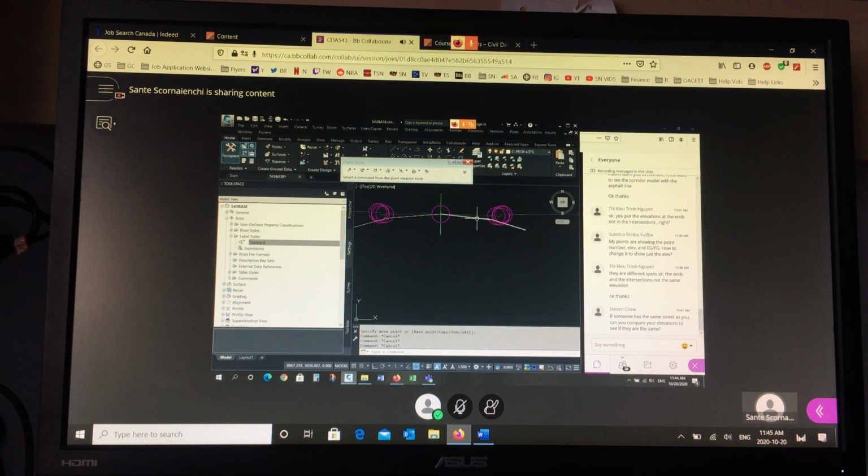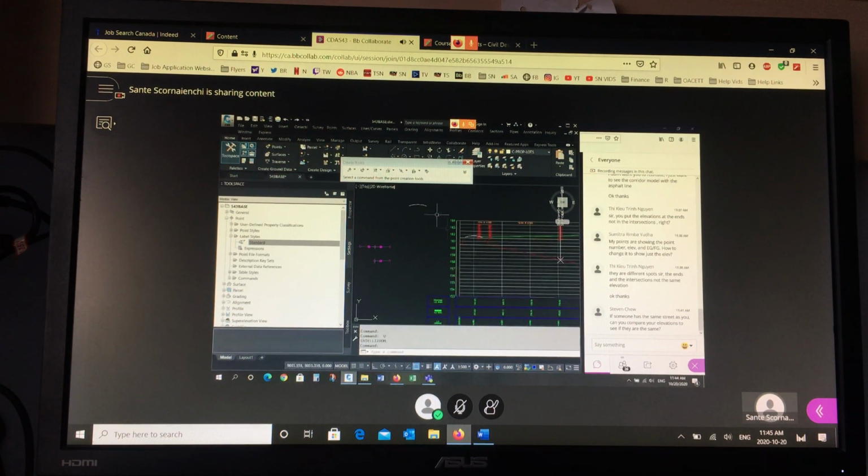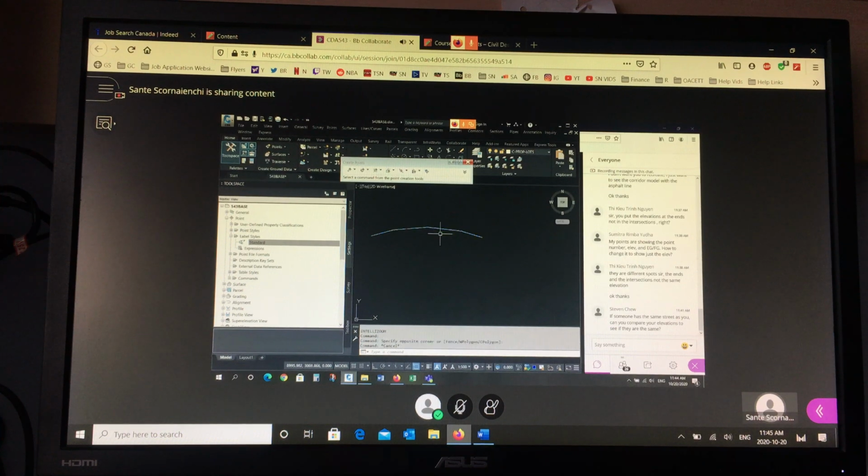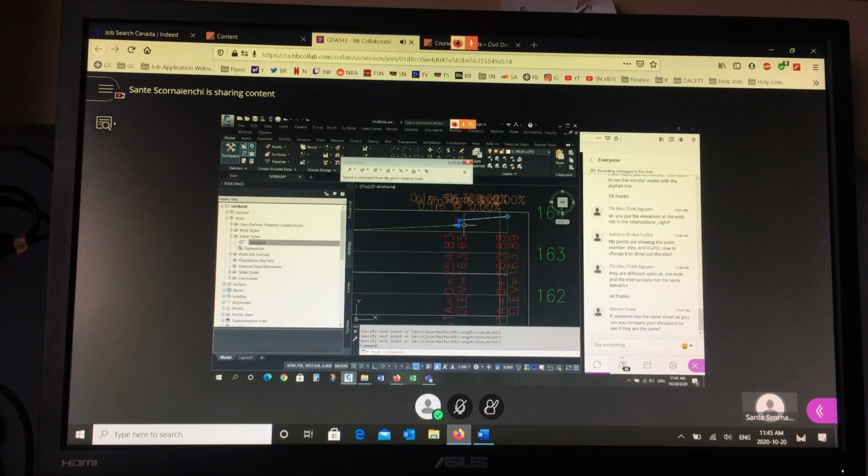And remember, this is vertically exaggerated, 5 times vertically exaggerated. So right now there's a shoulder with a ditch. I want it to have a boulevard in the future. So what that looks like in the future is this. We're going to keep the asphalt pavement, but we're going to have a curb and gutter that goes down. Actually, I can take this from here. Polyline, I can go from here to here to here. This is 5 times vertically exaggerated, remember?